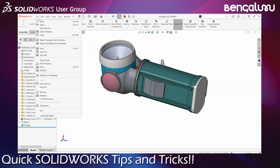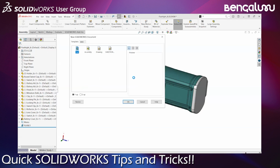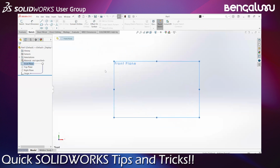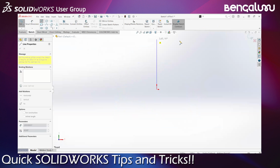I'll just start with a simple sketch. File, start with a new part. In SolidWorks, we have an option in the settings where, whenever a user creates any sketches, we make sure that we automatically add these relations.